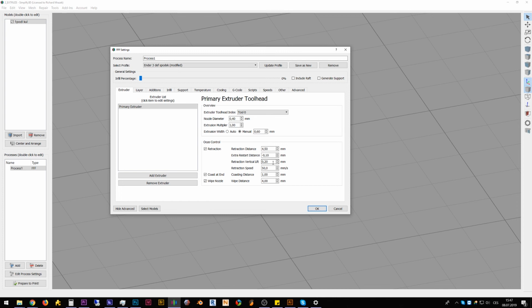If you have tall prints, you can meet problems. The nozzle will hit the print on the top side during movement, and it will break your print from the hotbed.